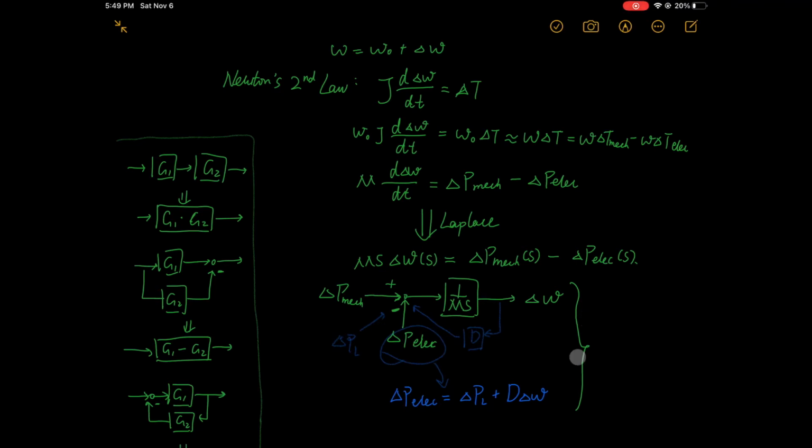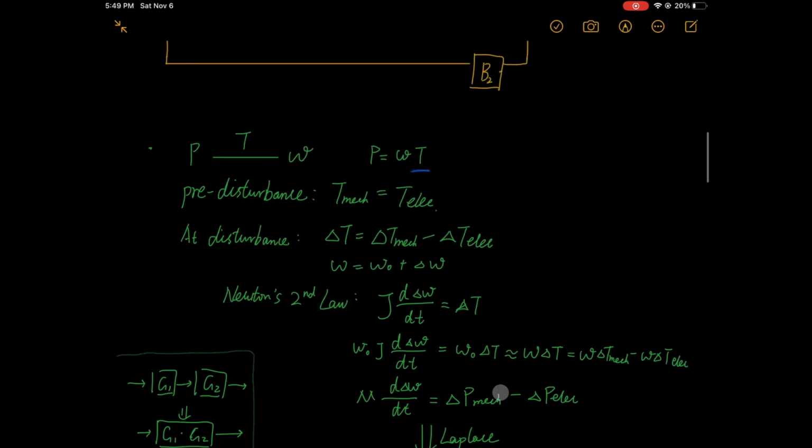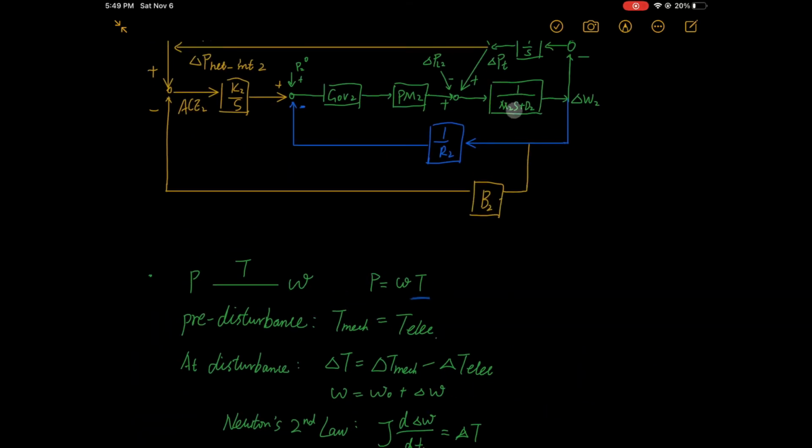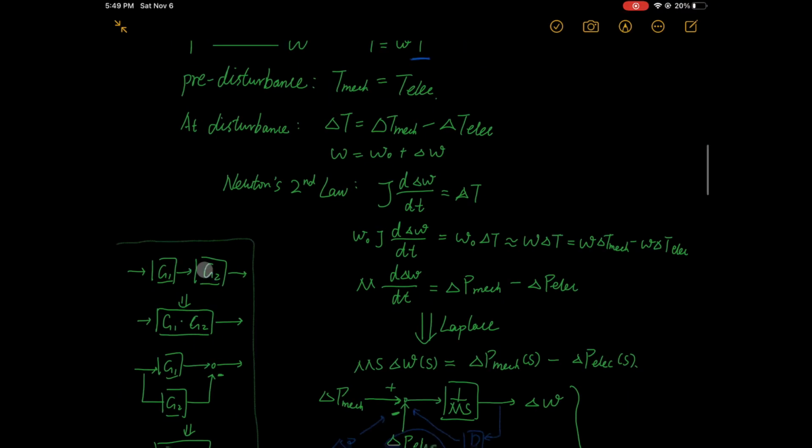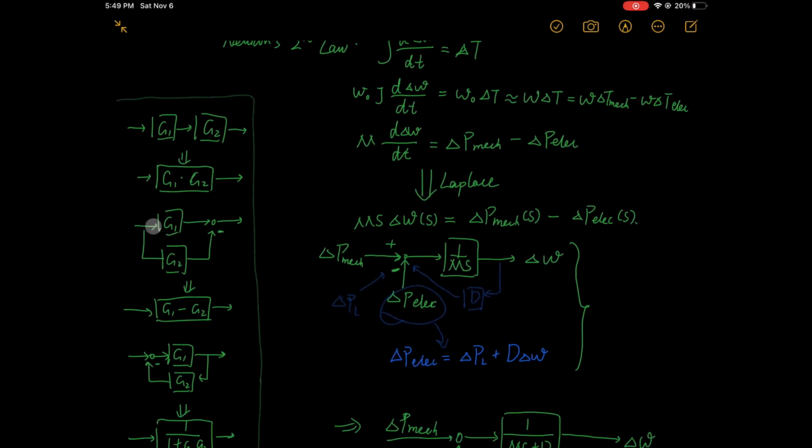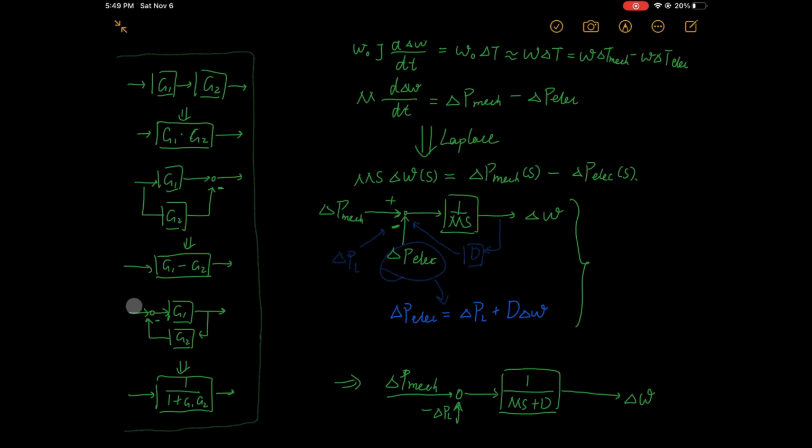The load can be further decomposed as frequency-sensitive and insensitive parts. The frequency-sensitive parts include induction machines and damper windings of synchronous machines. If you see terms in this diagram whose denominator is a summation, then there is a merging of feedback control blocks like this.